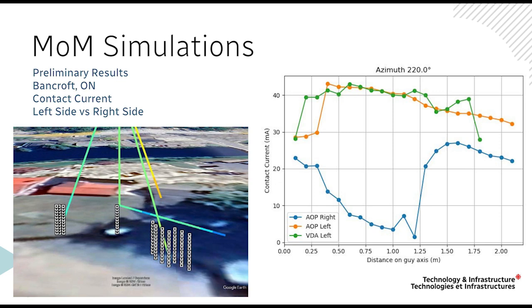If you touch the contact here or here, you would get widely different results, but you're touching the same place. That's what triggered us into thinking that the place where you are actually influences the contact current that you're measuring. So that's why the matchstick model depends on the position where you are when you do the contact current.